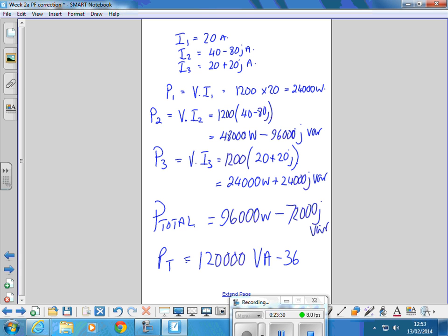So that gives you your apparent power in VA, and that will tell you what the phase angle is. You could then do a cos on that phase angle and get what the power factor is for that circuit. Everyone happy with that and happy they could do that maths? Yeah?